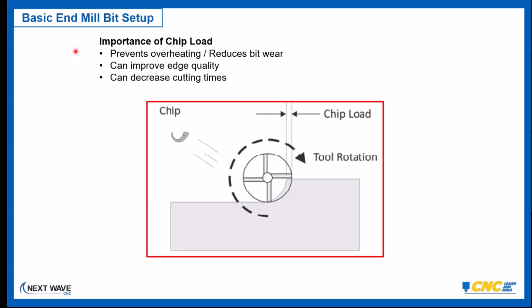And carbide itself is highly heat resistant, but the bonding agent has some limits. So if you overheat the bit, the bonding agent starts to break down and those little carbide crystals start to break off or fall off of the edge of the tool. At first, it's hardly perceivable and you really can't see it. But overheating a bit is a sure way to dull your bit prematurely.